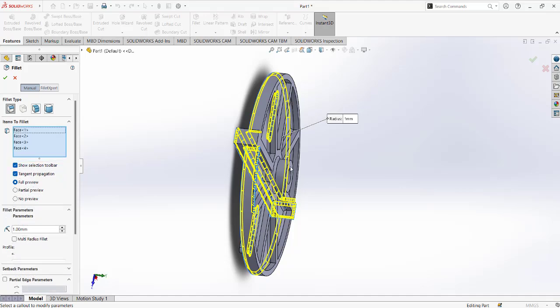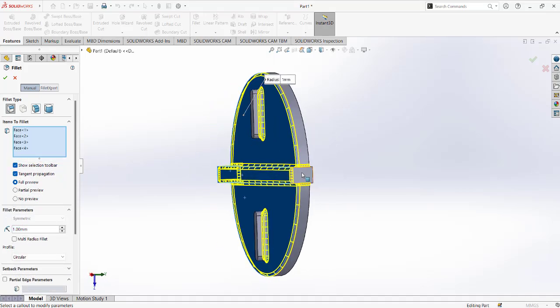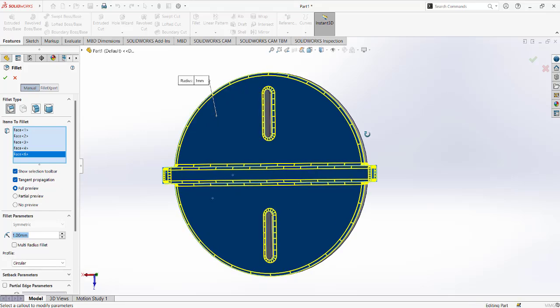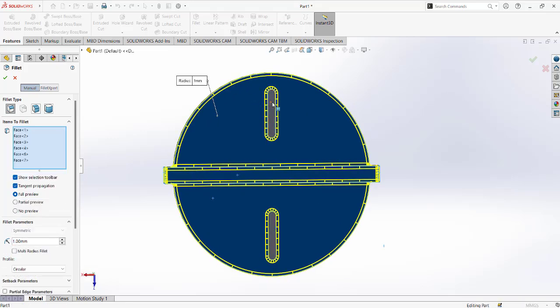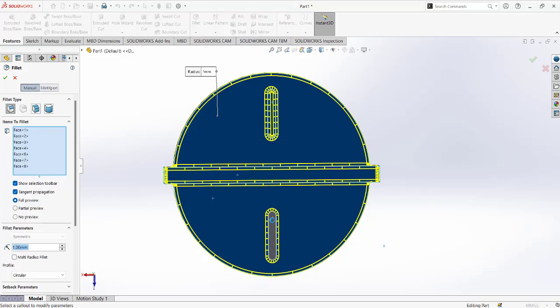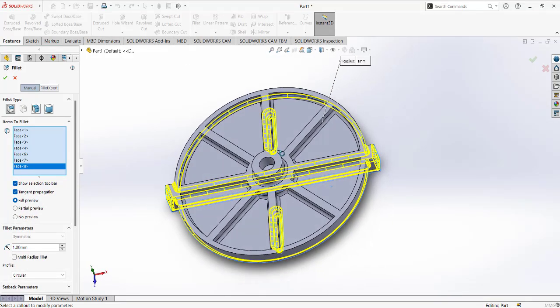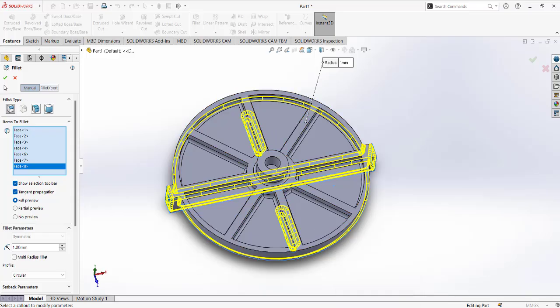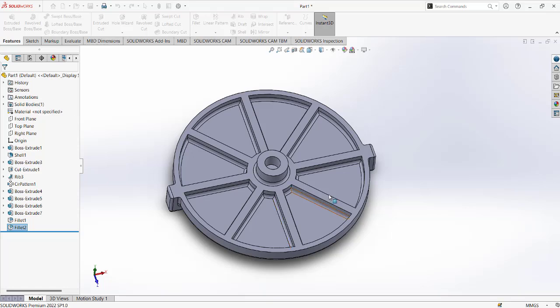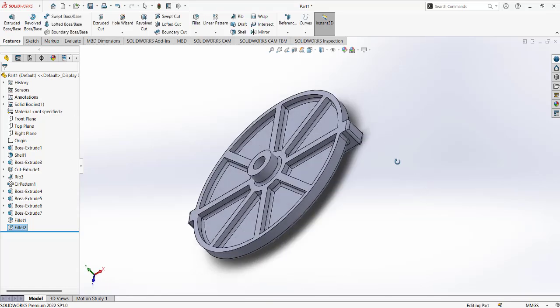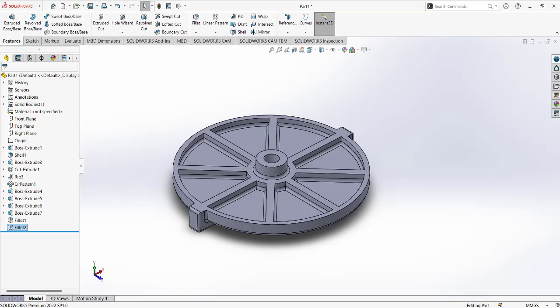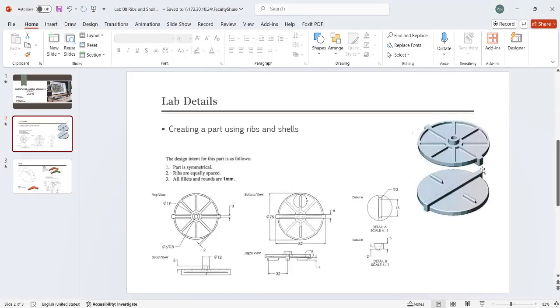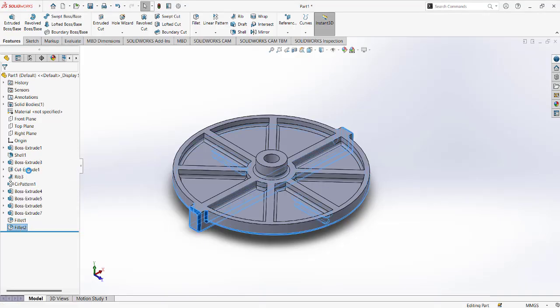I'm going to remove this one, last one that I selected, fillet on this face, fillet on these faces, and let me check if it's on the top faces or not. Yeah, that's it. So here you can see the details of the compact disc. I think that, yeah, sorry, these edges, they do not have the fillet, so I need to edit this portion.